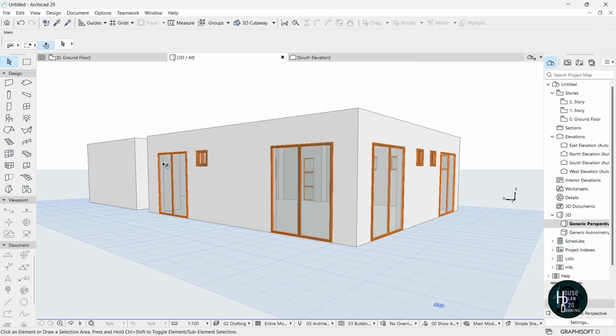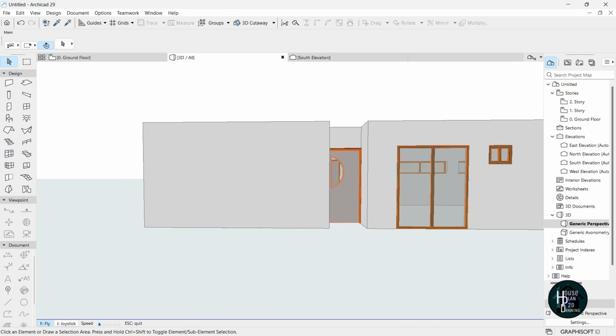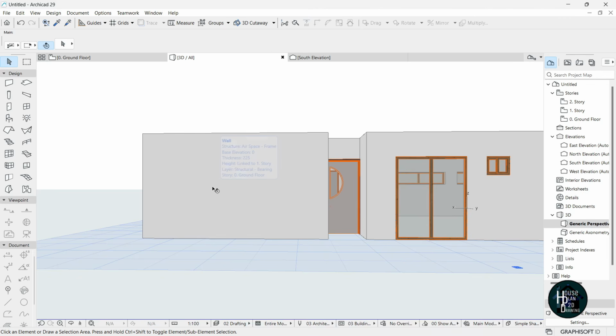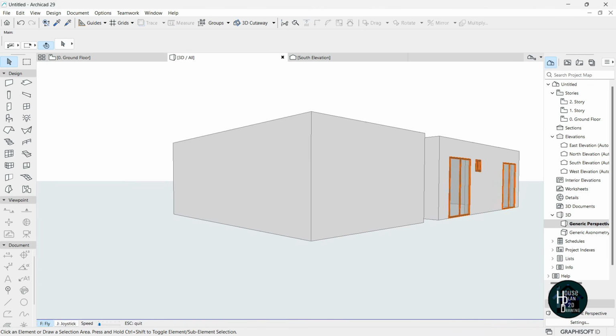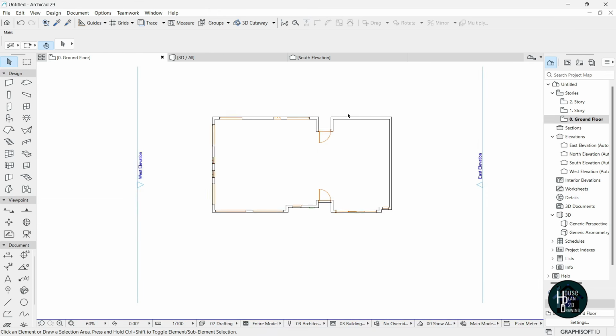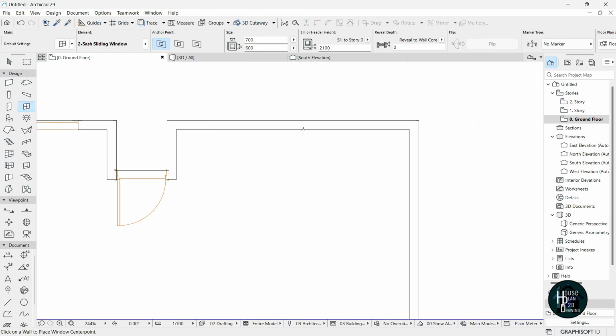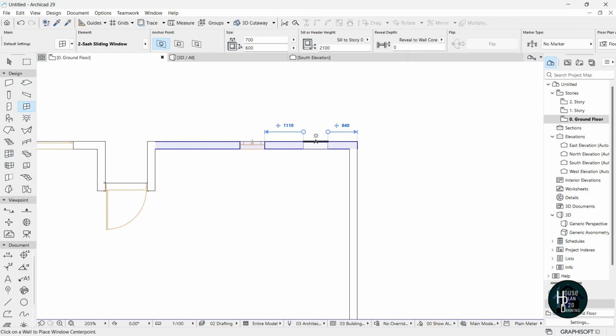As you can see, use something similar. Yeah, it has to look something like this. Okay, so we're fixing our door here. So the next thing I want to do is fix, there needs to be a window here, and some windows here too. Okay, so let's go to the ground floor plan and set that up. So I'm going to hold on Alt. I'm going to select this window. That's a toilet window. I'm going to place one here, and place another one here. All right, click this, press Ctrl D and try and move this to the middle.